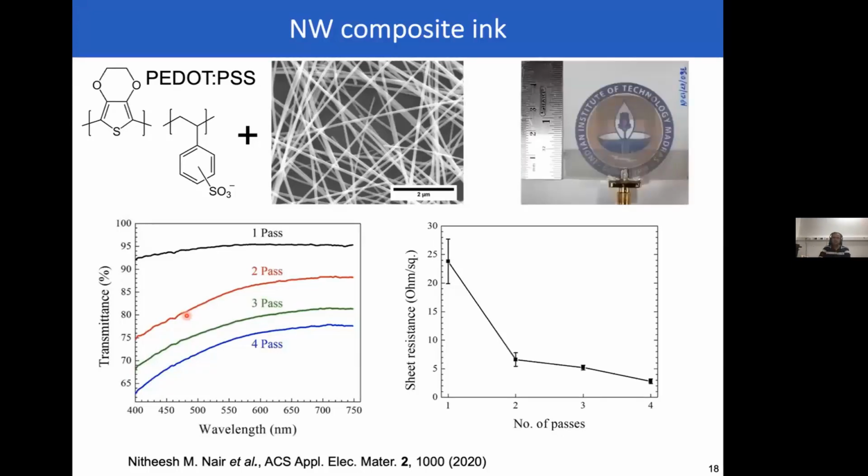So now we have this. We decided we'll do something different. So we fabricated a dual band Wi-Fi antenna. This is an antenna that works in the Wi-Fi frequency range, but it actually has 2 bands. One, I think, at 2.2, the other at 5.6 gigahertz. Now, this is a flexible, transparent antenna, and we also tested this against a commercial antenna that we purchased offline, and we find that the performance of this antenna is comparable to a commercial one.